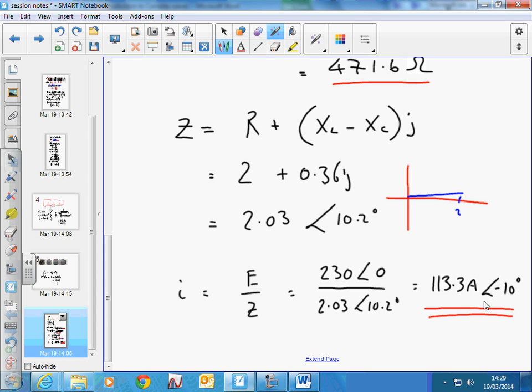We're driving not at the natural frequency but at the third harmonic, which is a multiple of the natural frequency. Sorry, the natural frequency is 150 rather, and we were driving it at 50, and it's likely that within there would be the harmonic, so we're hitting the natural frequency of the circuit.